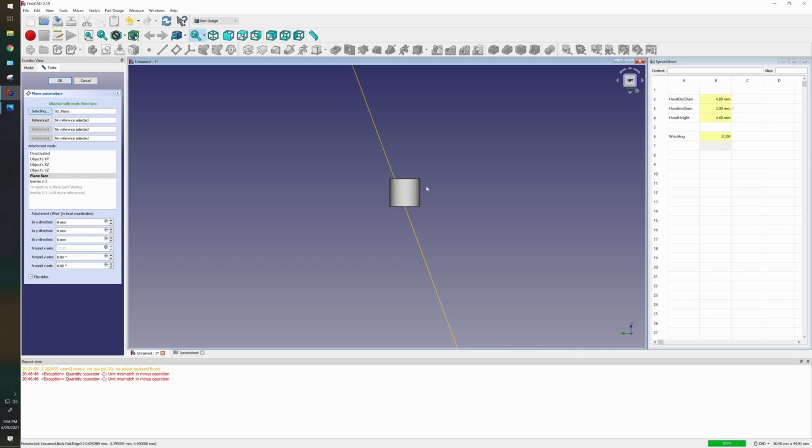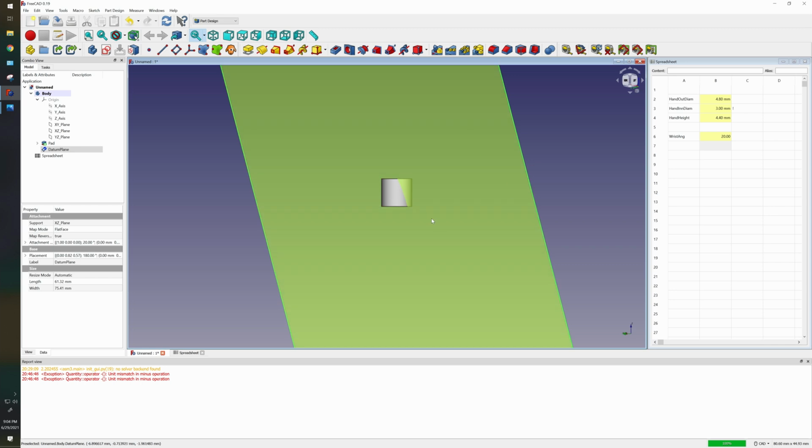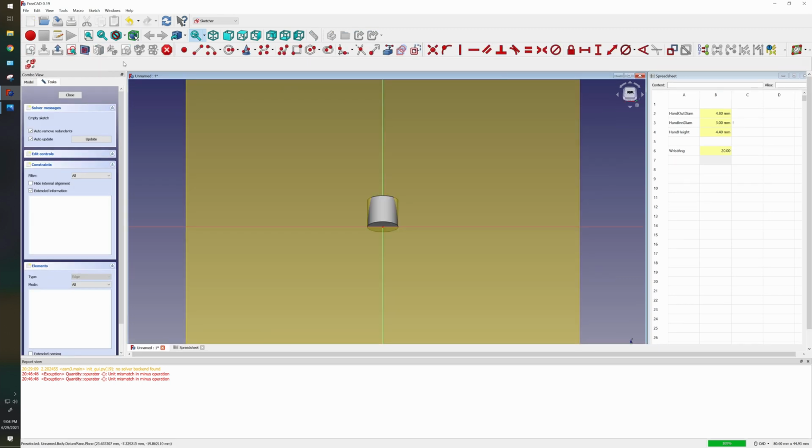Beautiful. That's great. So if I select this plane, and then I go to sketch, guess what? I can now sketch on this plane. So we'll put our circle in. And of course, see how it's all in the background again? Our magic button here for one editing mode, switch between active and full view. Switch to the active view. Cuts it out, lets us see. It's a beautiful thing.